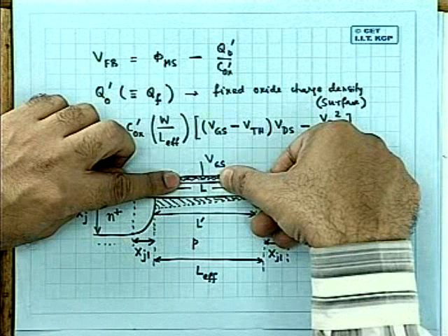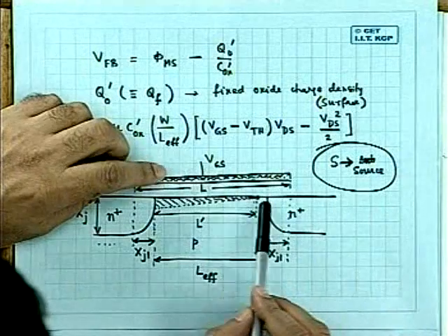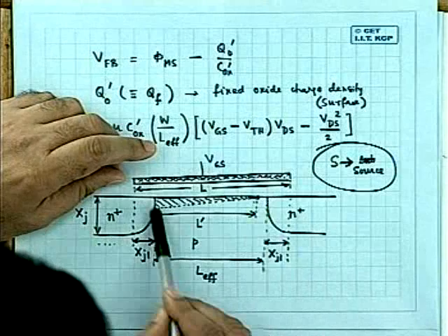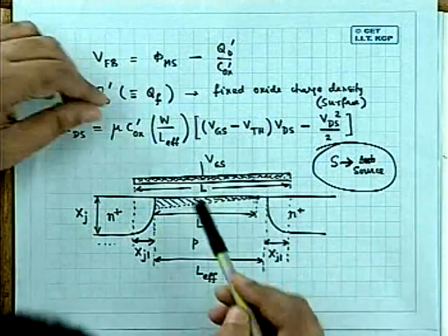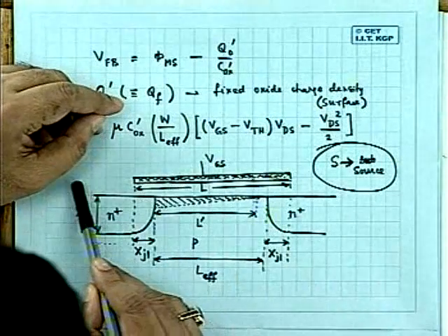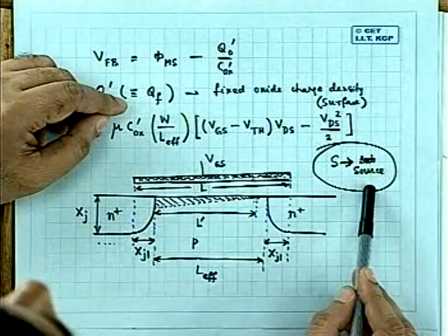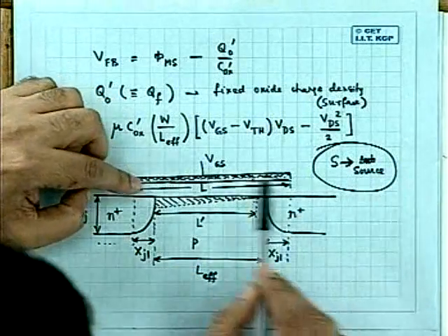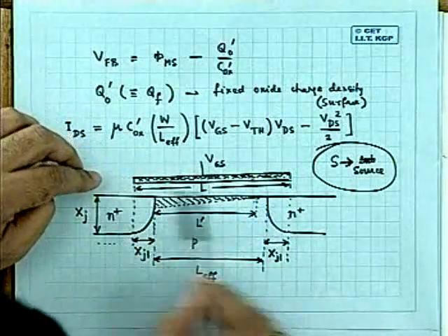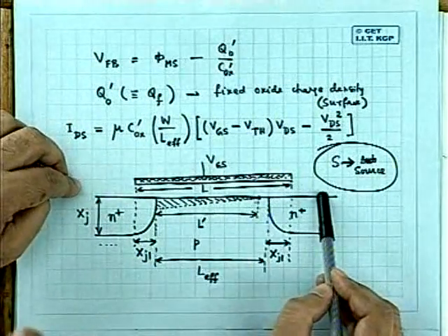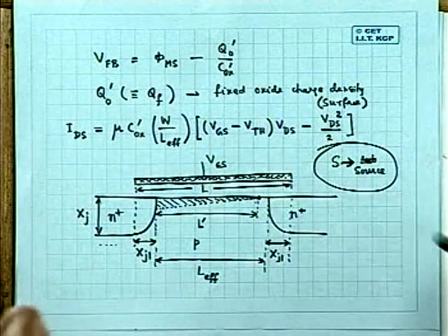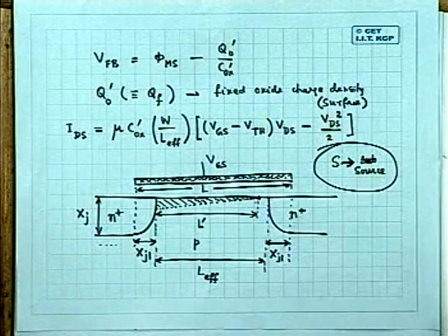In fact, in that case, what people were doing, this initial source drain diffusion could be done later, not initially. You have a very thin gate oxide, deposit polysilicon, define the polysilicon gate of length L, then remove the oxide, okay, and diffuse phosphorus or boron, depending on the technology.